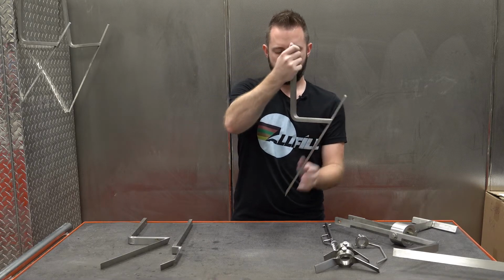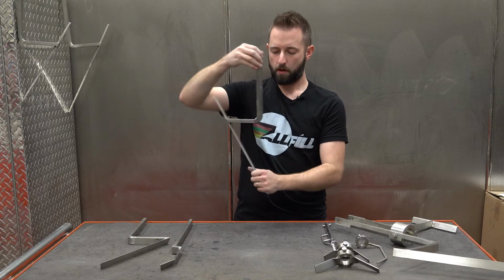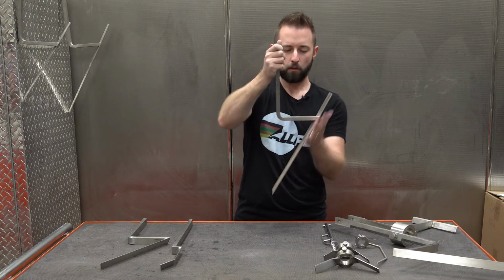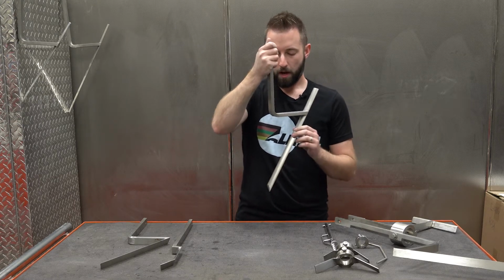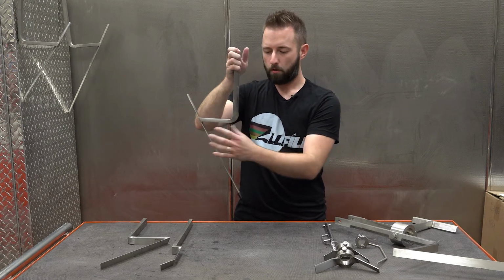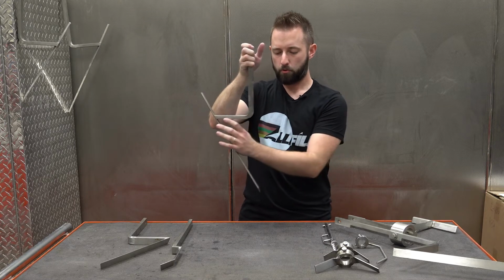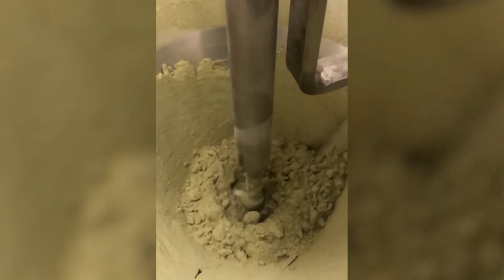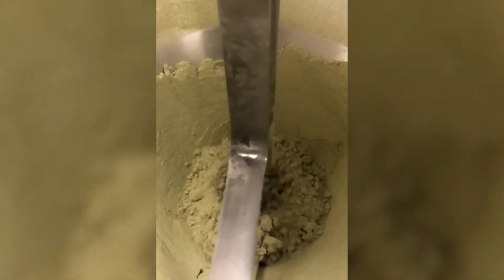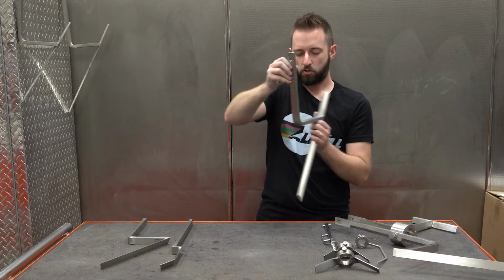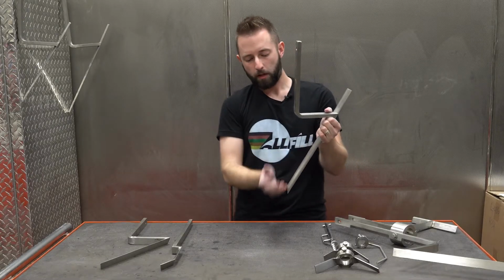This sweeps the outside edges of the hopper, following the profile of the inside of the conical hopper. As it's doing this, it's grabbing all the product inside the center of the hopper, dragging it and causing it to collapse down into the auger overflight, allowing it to drag that product through and run as efficiently as possible.